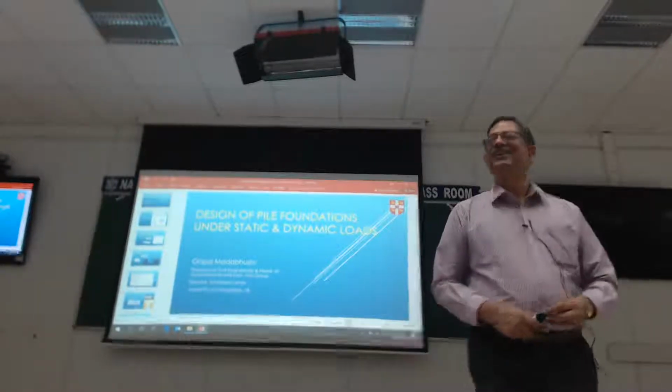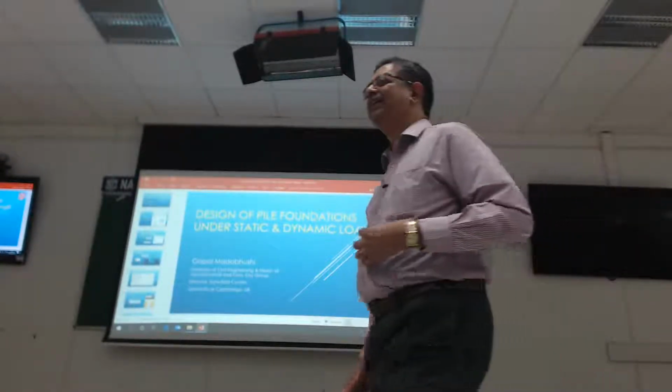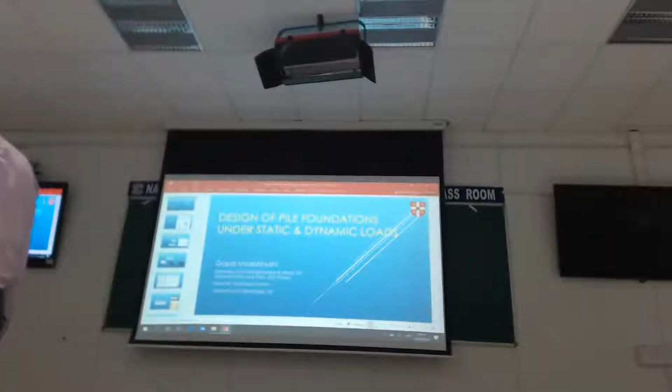Okay. Any other question? Yeah, sorry. We still have to do shake table tests for pile foundations. What suggestions or precautions do you have? Somebody else was asking this question earlier. It's really tricky to do that, unless you have a really large shaking table where you can carry a significant amount of soil. Most shaking tables I see are about this big. You can only make containers that big.